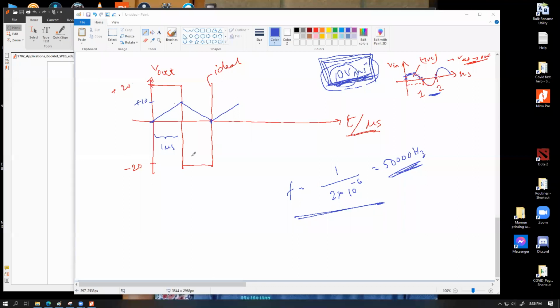The output will not be equal to the input. Input can be very small and input is usually very small. The output will become equal to the supply voltage. That's what saturation means. Is it like the input voltage, for what reason is it becoming less than the supply voltage? Are you asking about the mechanism, what happens in the op-amp for which we have this kind of output?